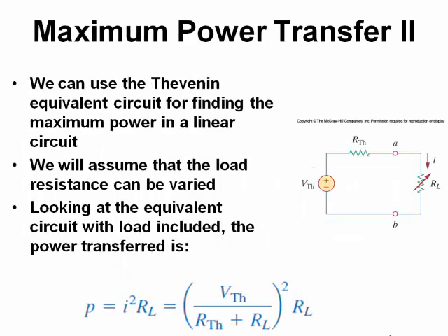So here's an example. This should look familiar from lab actually, of doing maximum power transfer. If I have a source right here and I've already modeled it into a Thevenin equivalent, so it's equivalent to one source and one resistor, there is a point which you saw in lab when this resistor is optimized so that you get maximum power across this resistor. And the source can supply whatever current is dictated by this circuit.